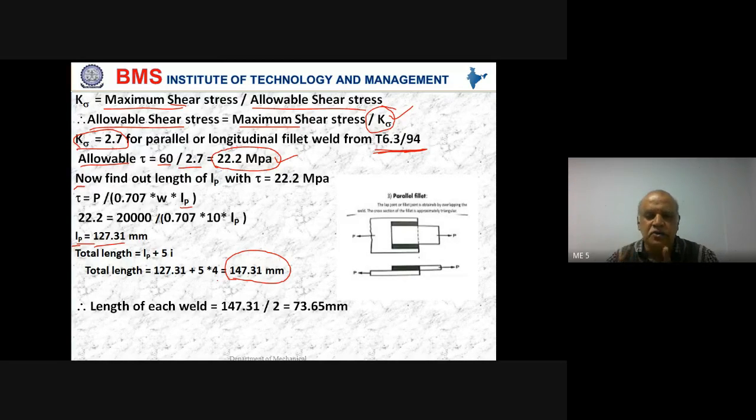If you are riding scooters, if there are welded joints, definitely it's going to break after say 20 days or 1 month of running it on rumblers at a speed of around 60 kilometers per hour, right? So when you want to have strong joints when riding in dynamic condition, we need to have more length of weld is what it all indicates. Is that okay?